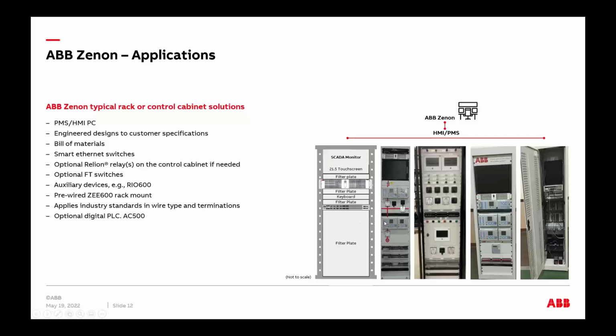Maybe they don't have space also for certain relays. They want you to put some relays on your control cabinet. You need to also plan for that as well. So you could see here, each control cabinet, depending really on the requirements and what situation you're in, could be just an HMI, SCADA monitoring system, or it has also other devices with it because you don't have space in the cubicle depending on the requirements.